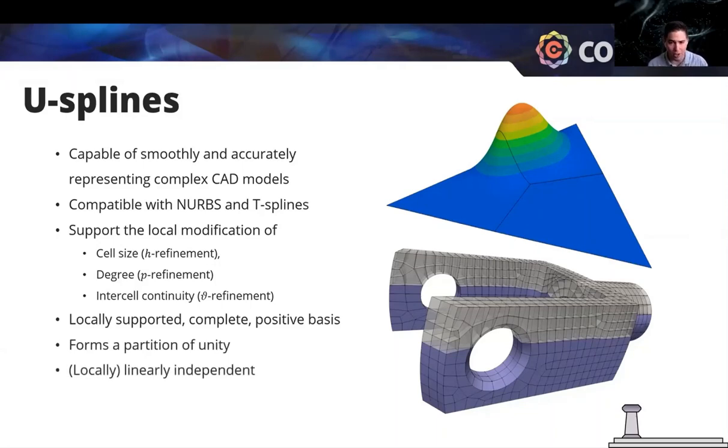And also, as you can see on the right, we support these in both 2D and 3D. On the top figure here is an unstructured mesh layout on a surface. We're showing one of these C1 basis functions on that layout. And then the bottom is an unstructured U-spline on a volume that is maximally smooth. So it's C0 where there are sharp edges, C0 on extraordinary points, to make sure that we've passed admissibility and we meet these requirements for the U-spline. But then elsewhere it's maximally smooth.